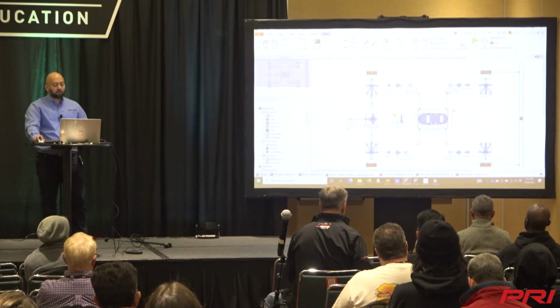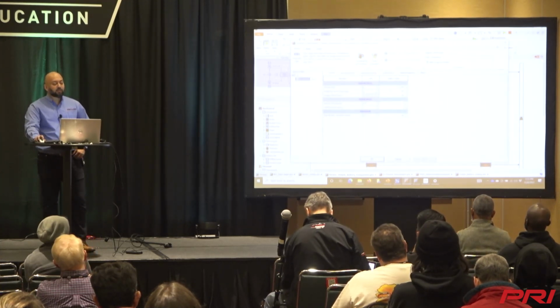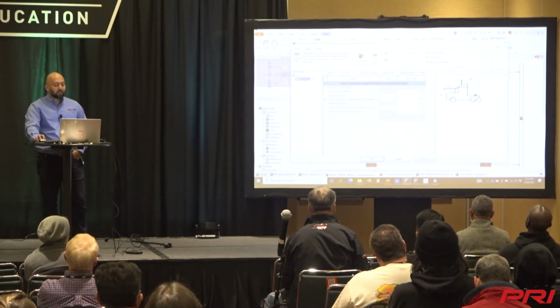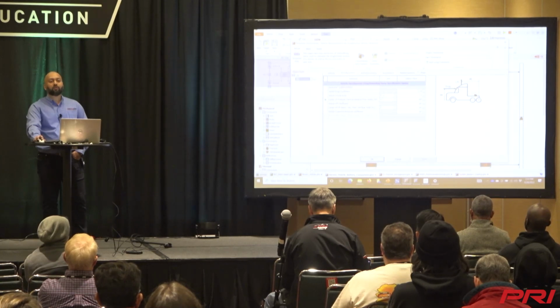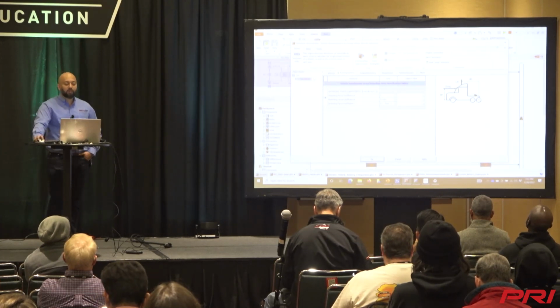The vehicle here is a truck. So we are feeding in the mass, the passenger and cargo mass. We are giving aerodynamics. Here you can see drag coefficient and frontal area. You can also use ABC coefficients, if you have them, to model the aerodynamics of the vehicle.